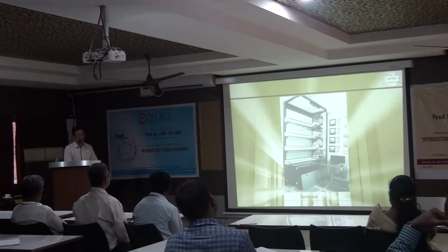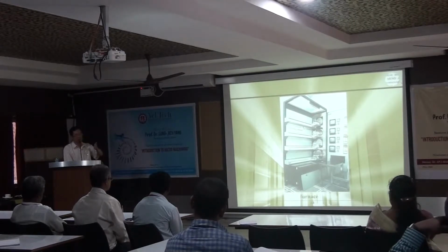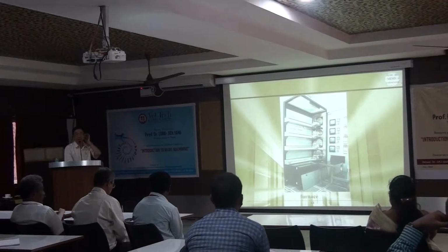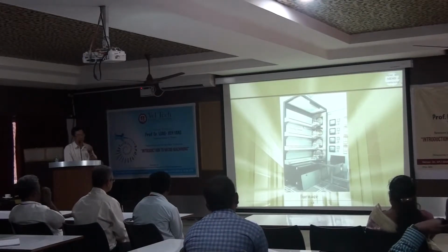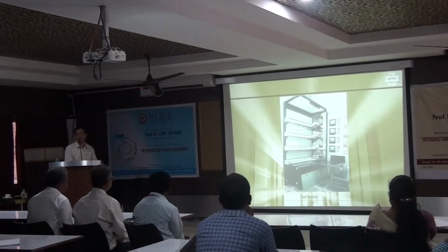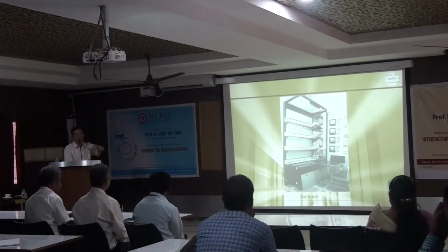So you should be careful about the surface tension. If you do not properly place the wafer inside, it's very easy to be broken. The silicon wafer is very easy to break, or even have plastic deformation, permanent deformation. If your wafer is distorted, the fab is useless.